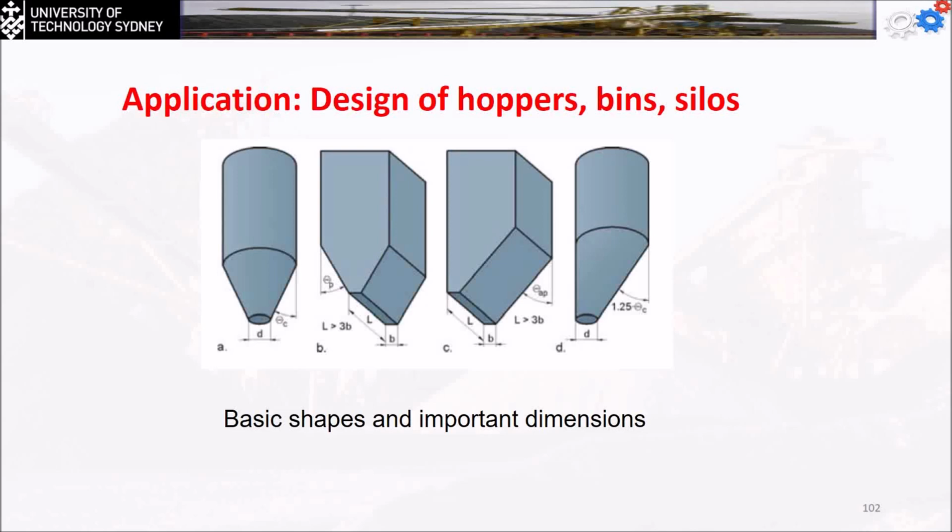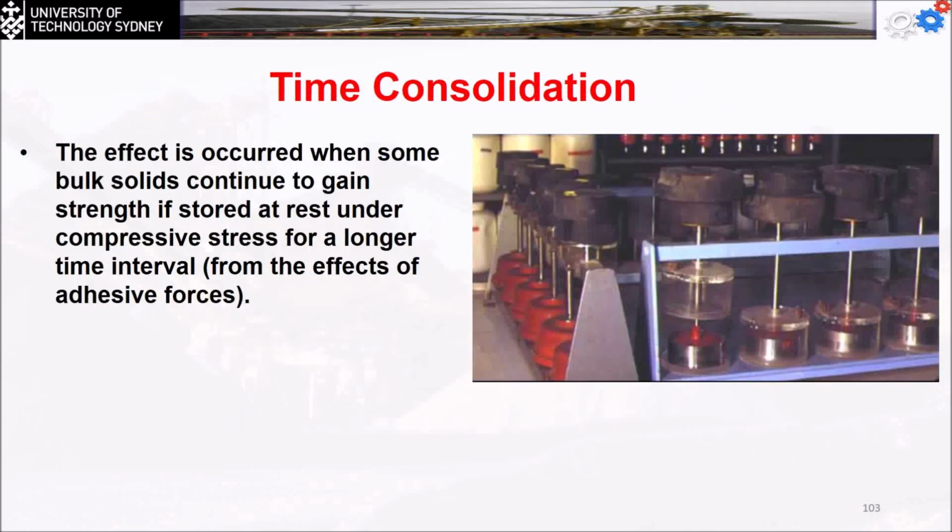Next is time consolidation. This is the test for time consolidation, but actually time consolidation happens naturally. We put any material in a barrel, leave it for a month, come back, and find that it has consolidated and is very hard to empty. The effect occurs when some bulk solids continue to gain strength if stored at rest under compressive stress for a longer time, from the effect of the adhesive forces between the particles.